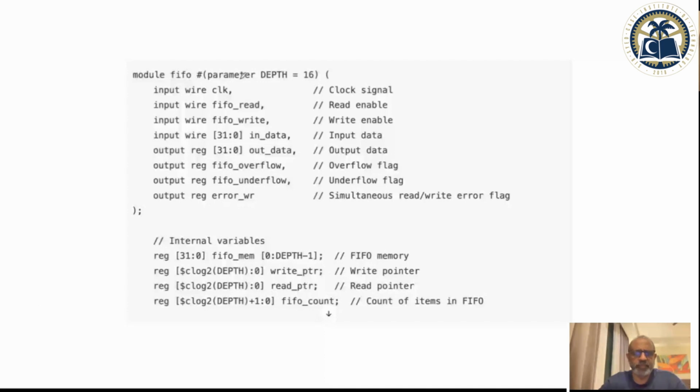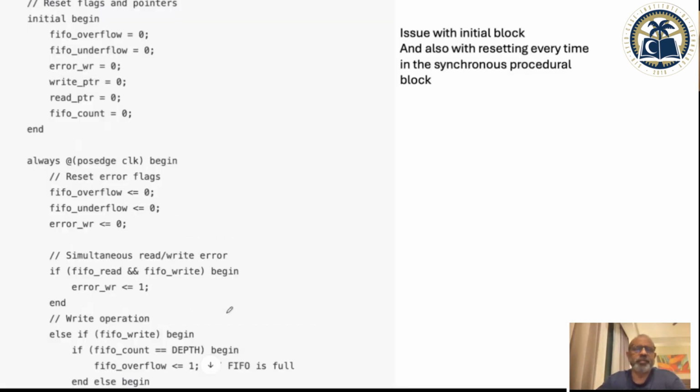You can change this number, and these are also parameterized based on the depth. It will take log base 2, assuming depth is always going to be a power of 2. Whereas Copilot has just fixed it to 4, which you can always go and change, or maybe define another parameter.